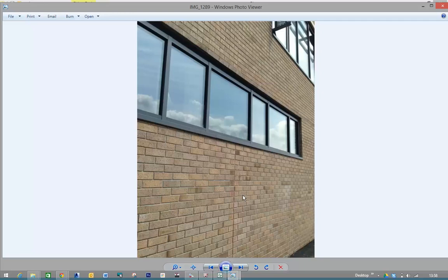So brickwork will expand as it gets hot. So typically no more than sort of 10 meters you put an expansion joint horizontally. We put them on steel. So ours are at 7.2. You must also put a compression joint no more than every 3 stories apart.